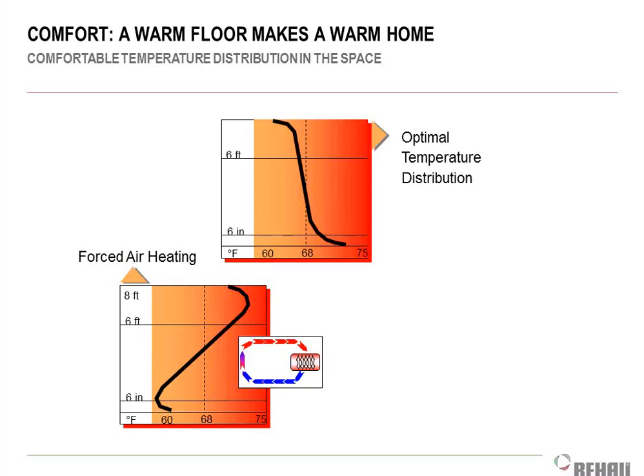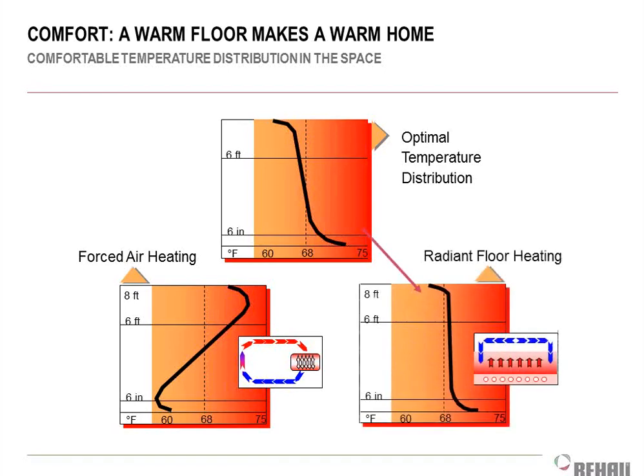Floor delivery systems are a lot better than overhead for heating anyway. So residentially, we do a little better with this. Commercially, we typically heat from overhead because it's a cooling-driven application, and heating is kind of a side thought usually. But the point is, with an air-based system, I'm not going to be able to keep that 5-degree delta T between your head and your toes. So it's going to, in general, be less comfortable. Radiant systems are really good about it, right?